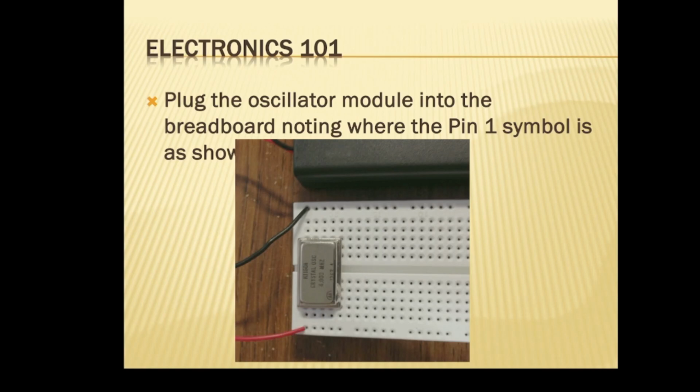FYI, a lot of overshoot. I'm on 5 volts per division, and I'm running off 4.75 volts. Karen, did you filter? No, I just went straight out. There wasn't enough output power to get through the filter. I paralleled resistors and still couldn't get anything through. You have to play with those values of capacitors a little bit. The capacitor was basically just taking everything to ground. But I wanted to show them it worked.